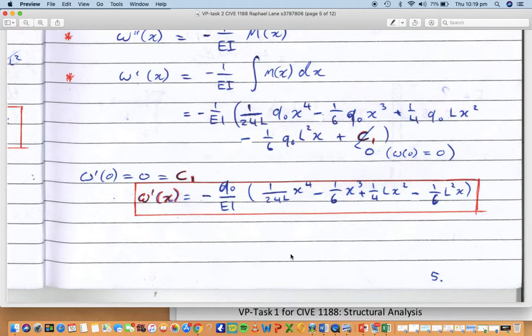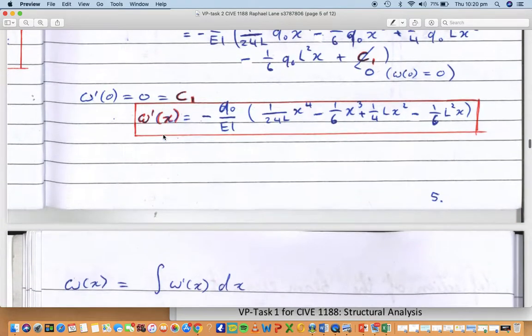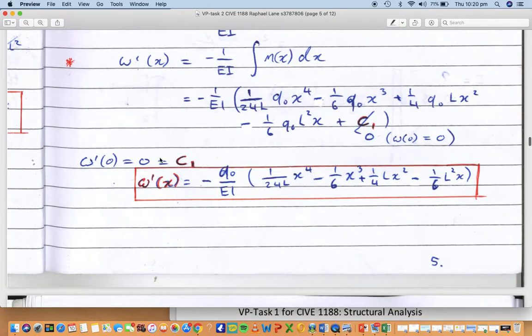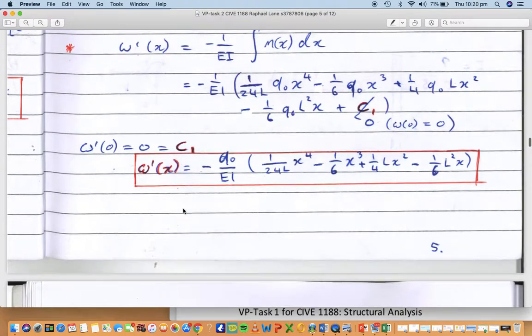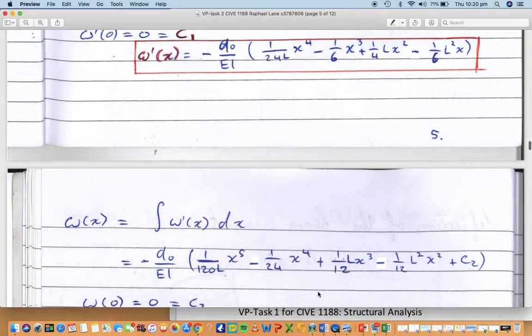Although the sign is most likely made out of aluminium, I thought that structural steel would be more interesting for the project. So integrating, I calculated a function for the slope of the deflection as well as the deflection, applying boundary conditions on the way to evaluate the integration constants.